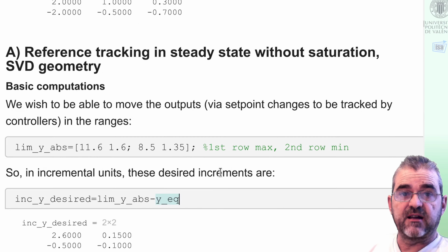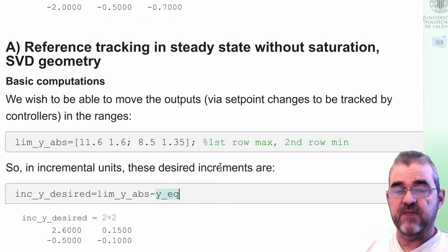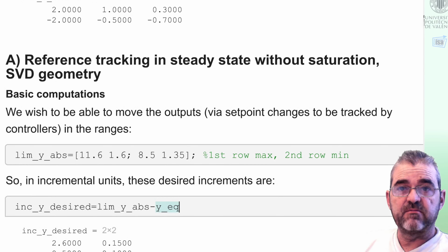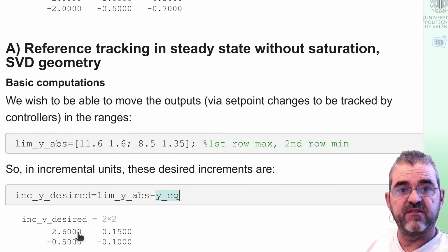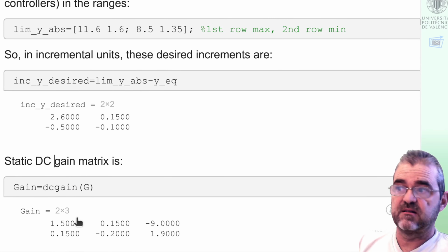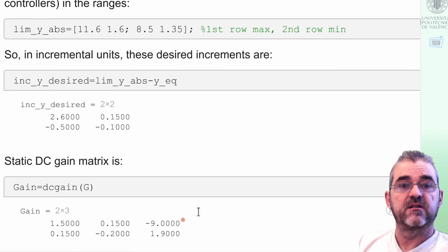And I will disregard the time taken to reach them. So dynamics, settling time, or closed-loop bandwidth will not be considered here, and I just wish to answer the question of whether a step in input within these limits will be able to reach the maximum deviation given by these desired output limits in steady state. So we will discuss only computations with the static gain matrix, which is replacing s by 0, this thing.